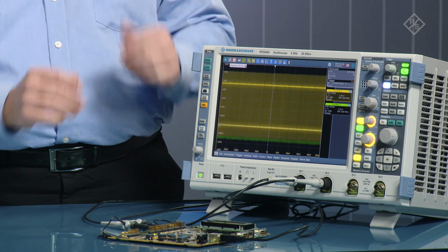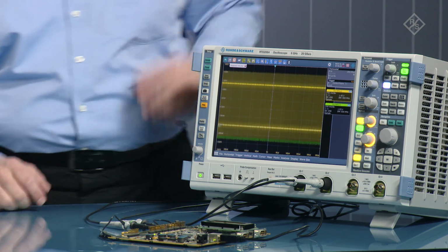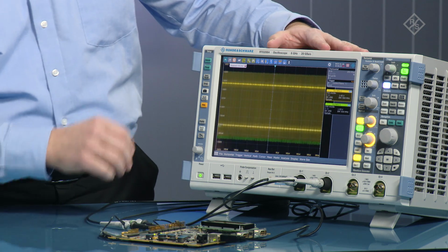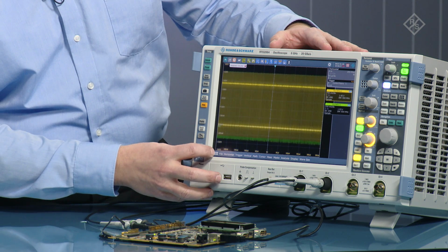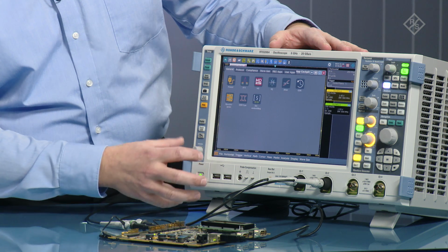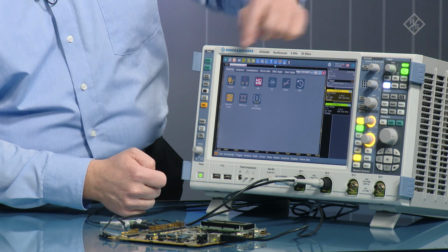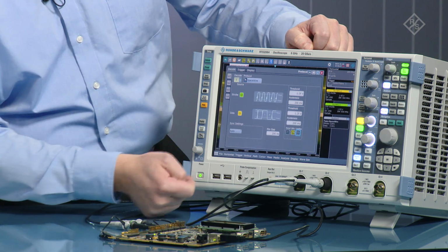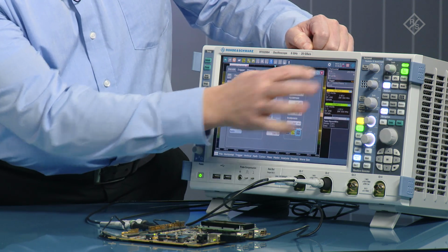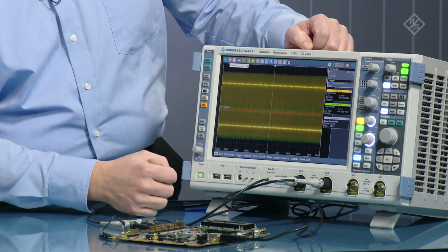Hi, I'm Matthias Beer, Product Manager for Oscilloscopes at Rohde Schwarz, and today we would like to show you briefly our instrument, the RTO, with a test setup we have prepared. We have here a demo board which is providing us data and a strobe signal, and for decoding the SpaceWire bus, we open our application cockpit and select the corresponding protocol, in our case SpaceWire, and we see immediately that the bus is decoded.